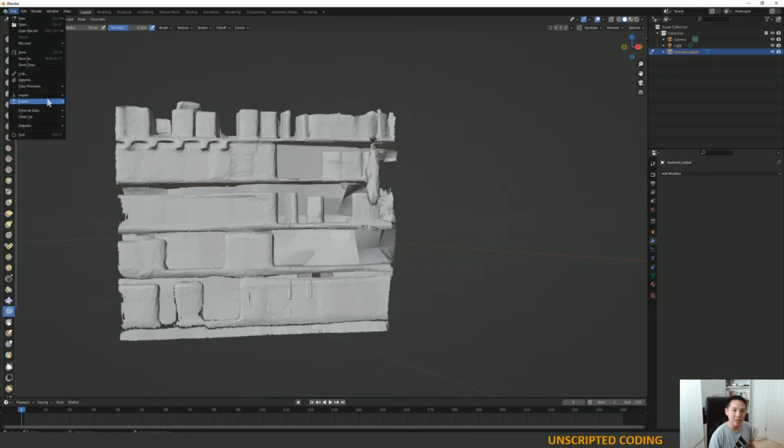So what I'm going to do is export on another screen this as an STL file. Most of the 3D printing software is going to be STL standard. So I'm just going to do this, export STL into that same folder, export it. It's going to take a moment. And we have it right here.